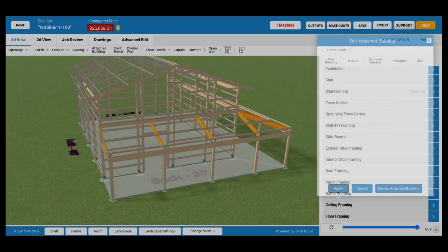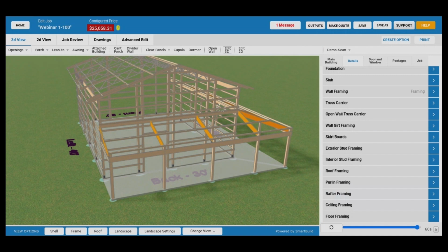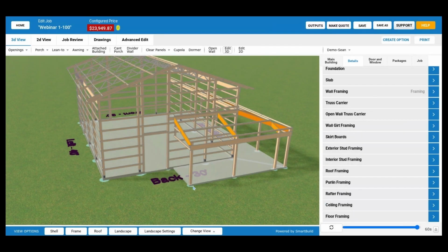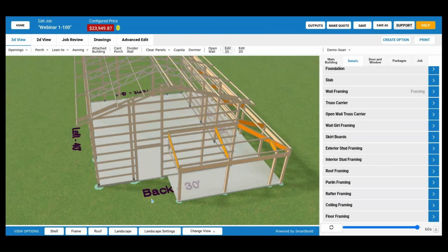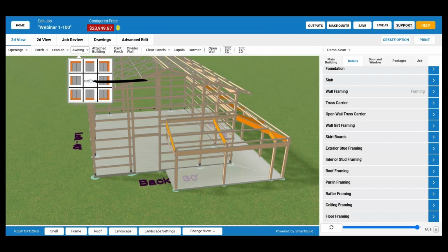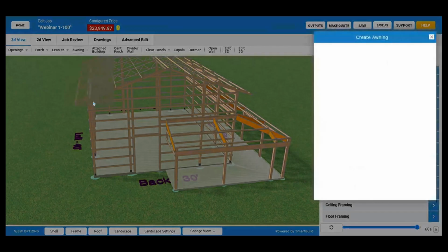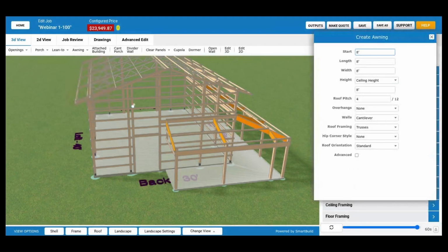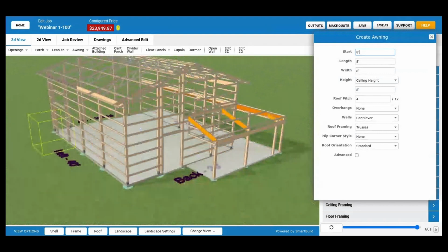Brandon says not overlapping. Let's say he has a 40-foot wide barn and the wraparound porch comes 16 across, and then you would like to put an awning over a garage door. Kind of like what you have here. So now if you go to porch or awning, you can do custom and you can add another one on the front. But if you try to use the full length, it gives you an error. So you can go from 0 to 15 or 0 to 10, but it wouldn't let me do it with 8.